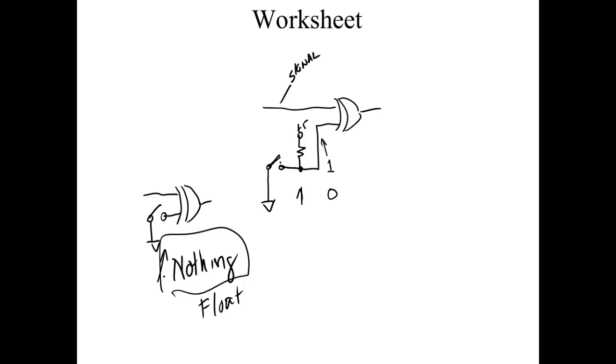We had a scale down in Calera, where on real cold days, it wouldn't work. On hot and warm days, it would. So in the wintertime, we would go down there, and it was out in a shed. What would happen is, the sun would come up and hit the shed and warm the scale, the digital indicator, up, and it would start working. At night, when there was no sun shining on the shed, the thing gave us the wrong reading. And guess what we found? Some engineer left an input to one of those logic gates floating. Nothing.